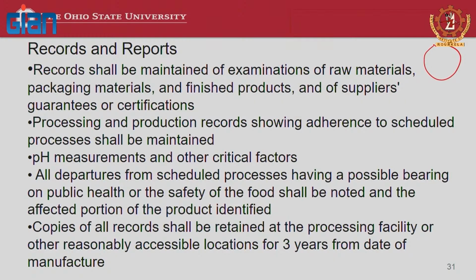If you have old canning equipment, it's going to have a circular recorder, and there is a pen that moves around the chart and records, at any given time, the temperature at which the product is being processed. In other words, this gives you proof that the particular batch of your canned product received 121 Celsius and above processing temperature. So, it records that information.